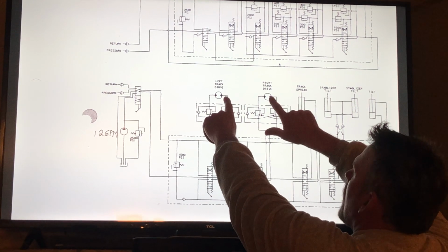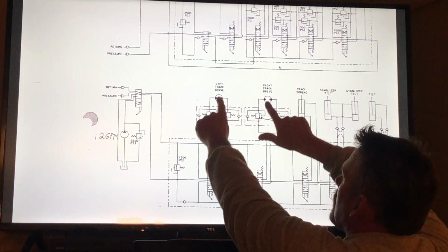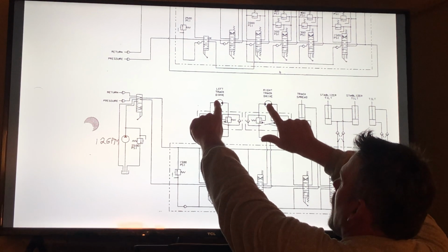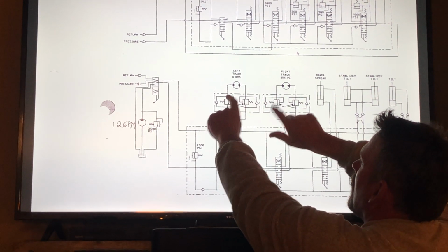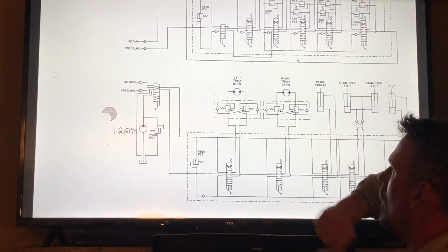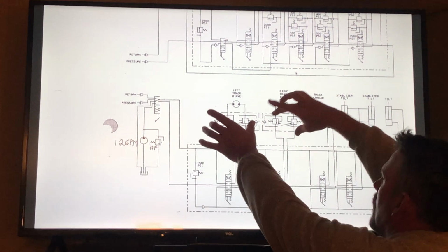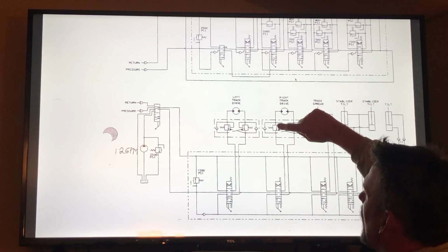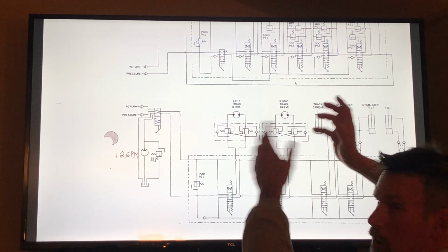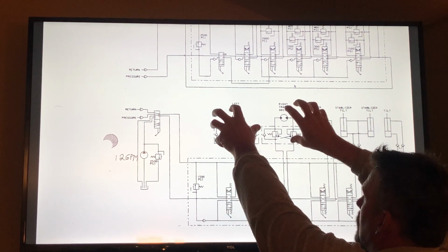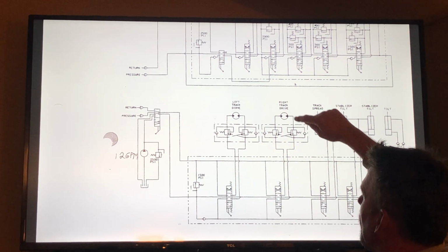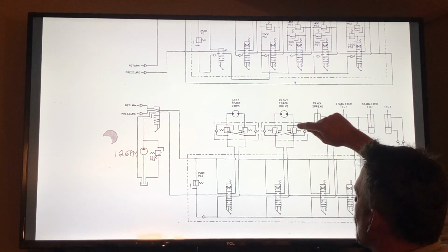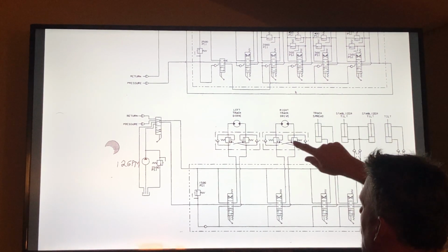So we have our oil come around here and it starts to turn the drive motors and then bang, it hits these valves, okay? Also inside, this is the counterbalance valve. So it hits against there and it's blocked. So the motors can't turn, okay? This pressure starts to build up from the pump, okay, that's going around here, builds up, builds up.